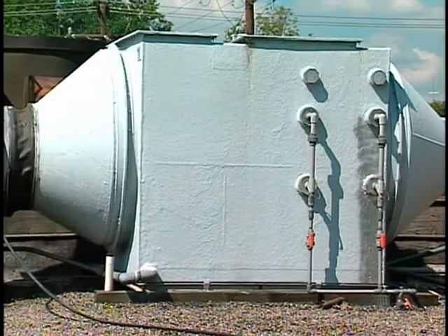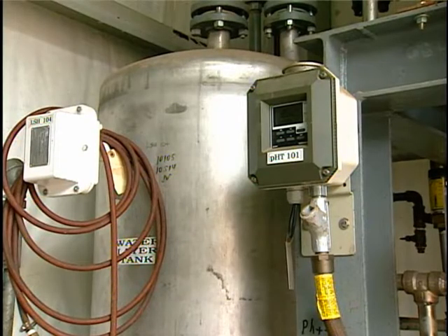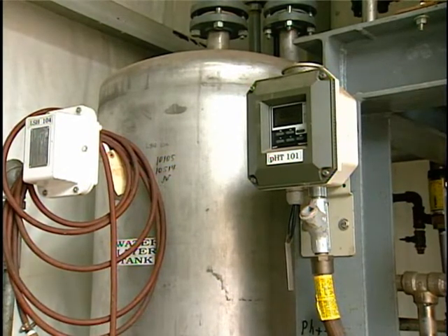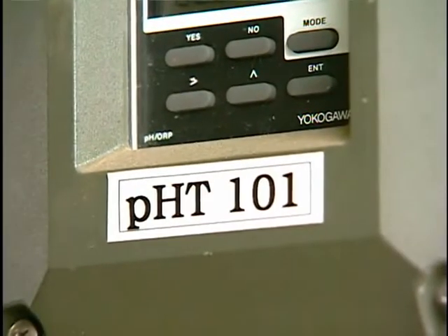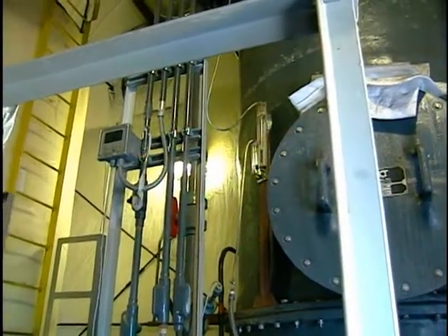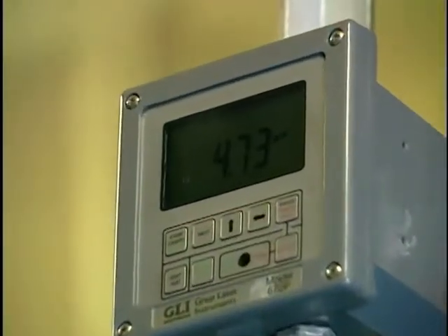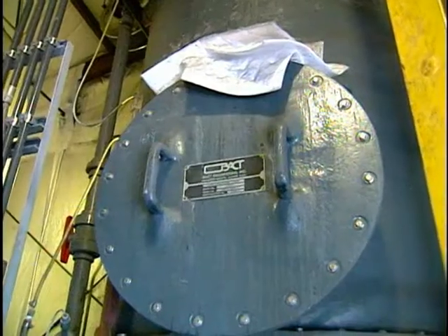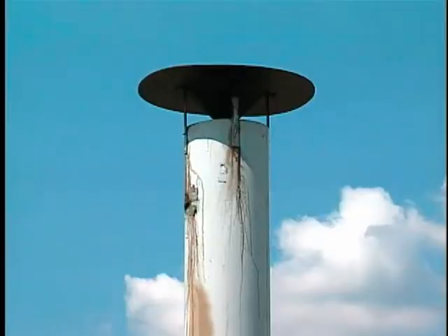The pH of the inlet and outlet liquid should be evaluated. An inlet pH above 10 indicates a potential for scale accumulation that can plug nozzles, packed beds, and trays, reducing liquid flow rates and impairing gas-liquid contact. On acid gas scrubbers, an outlet pH below about 6 indicates that insufficient alkali is being provided to neutralize the acidic gases being absorbed, reducing the collection efficiency. Also, when the pH is below 6, severe corrosion of metallic components is possible.